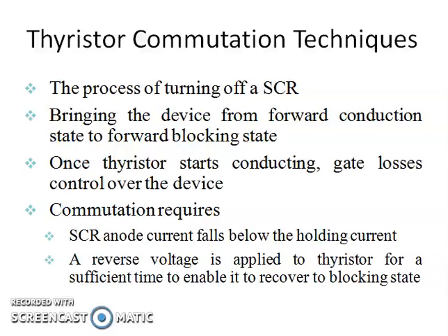Thyristor commutation techniques. What is meant by thyristor commutation? The process of turning off an SCR is known as commutation of an SCR. Turning off means bringing the device from the forward conduction state to the forward blocking state. A thyristor is turned on by applying a signal to its gate cathode circuit.